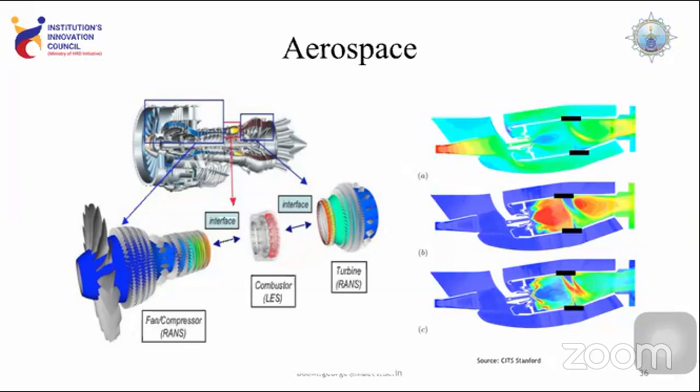When it comes to an actual engine like this, with a computational fluid dynamics simulation, in the first figure A you can observe a void region shown in the center as the blue area, which shows the negative pressure contour that is developed. When there is an impingement of flow into that, figure B shows the propagation of the flame, and how, as combustion progresses, the excess air is circulated. So I can keep on doing this experiment by varying certain conditions and parameters.